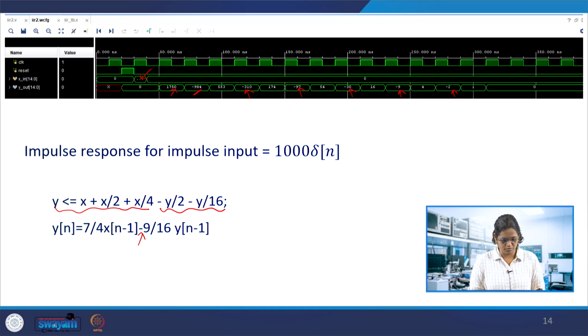Okay, so of the filter which is having only one delay at the feedback and one in the feed forward. So this case is just to indicate the alternate signs, and the same thing you would be able to simulate and see the response in MATLAB as well.